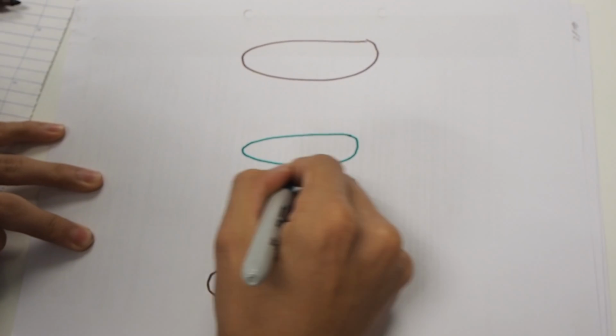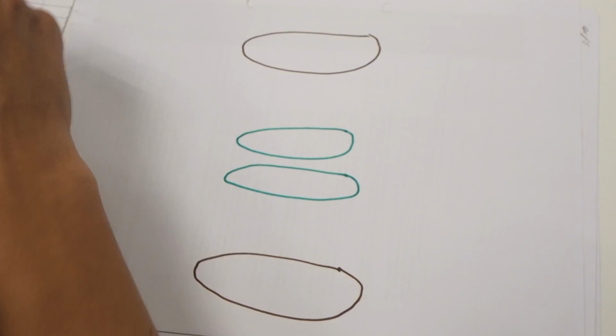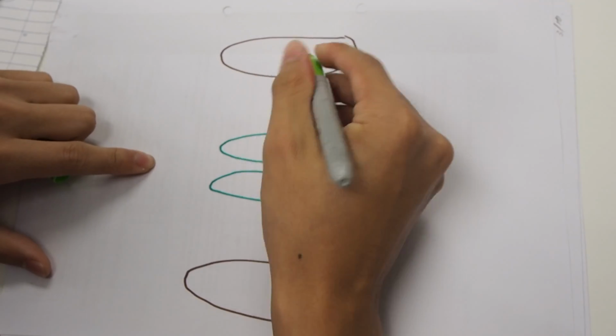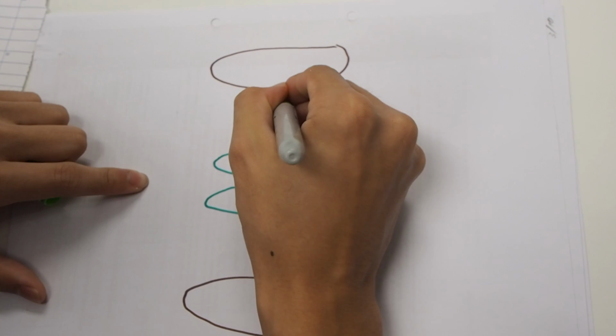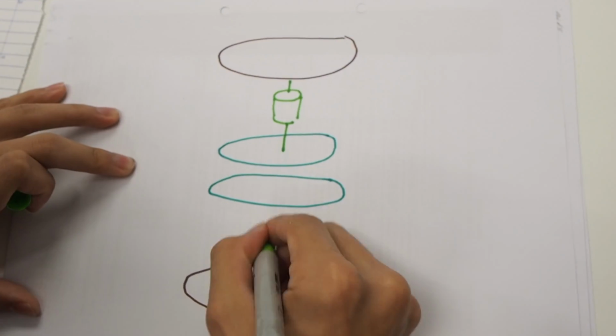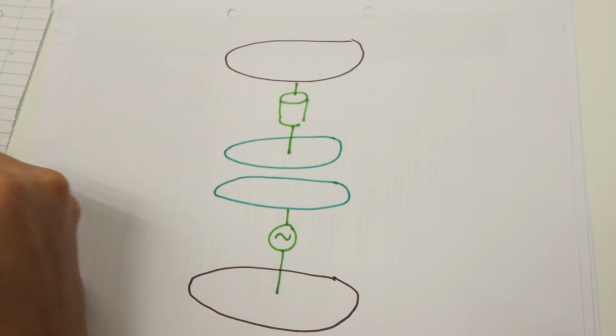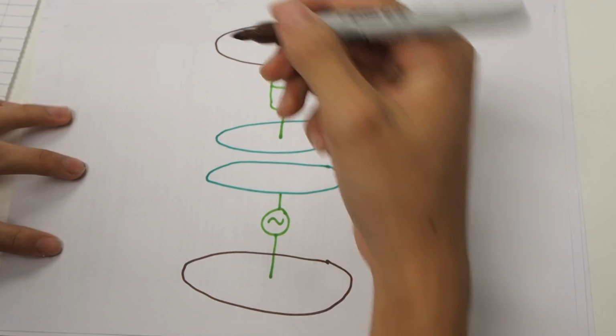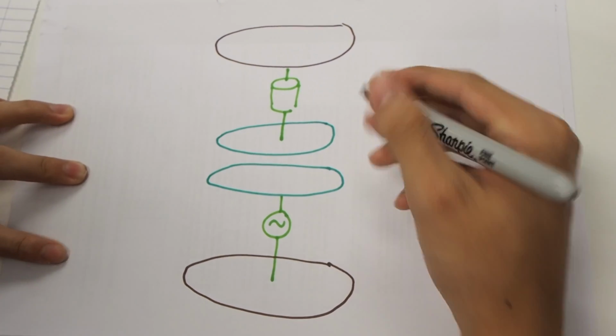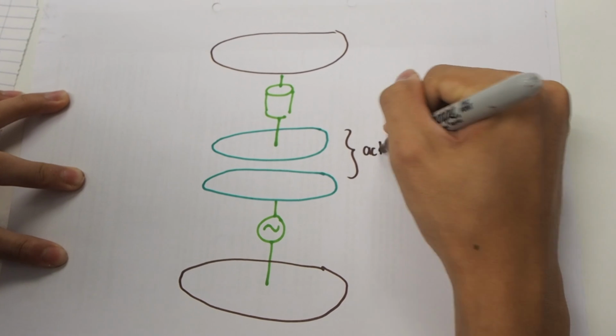is a reactive device. It responds to different frequencies in different ways. To low frequency signals, it has a very high impedance or resistance, so low frequency signals are blocked from going through. To high frequency signals, it has a low impedance or resistance, so high frequency signals are passed through easily.